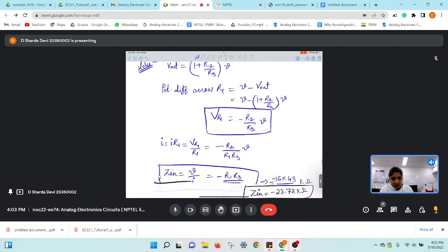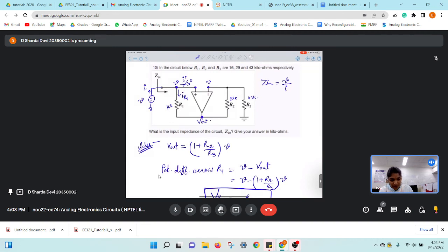And if you carefully observe this particular circuit, what is happening is at this particular node, when you say drop across the resistor, we are saying plus minus VR1, right? Here the negative terminal voltage is higher than the positive terminal voltage. That's why you are getting this negative resistance type of behavior. So the more you increase your input voltage, the current will reduce, or you will get current in the opposite direction. That is the basic idea in this particular case. Is this clear?